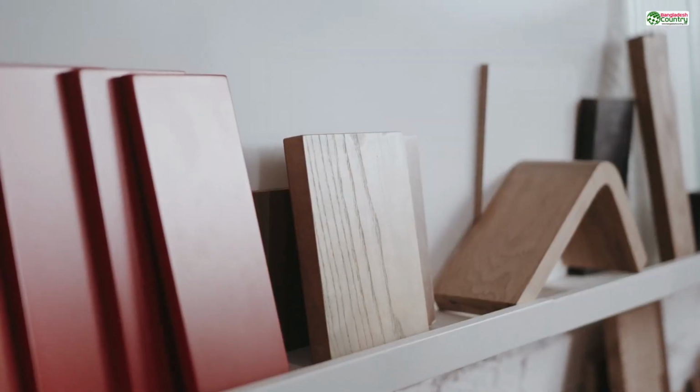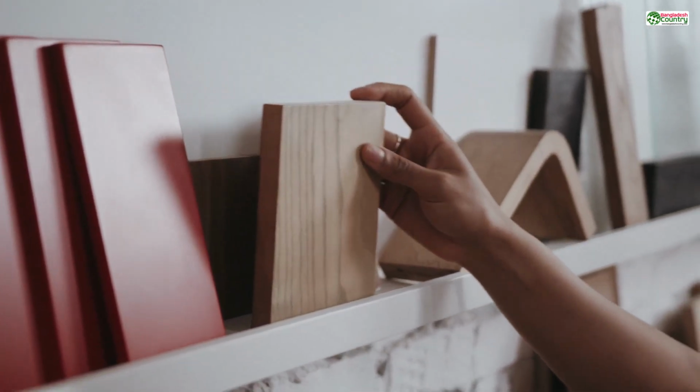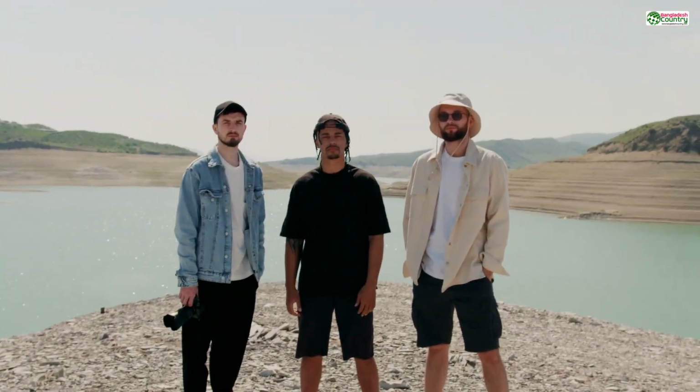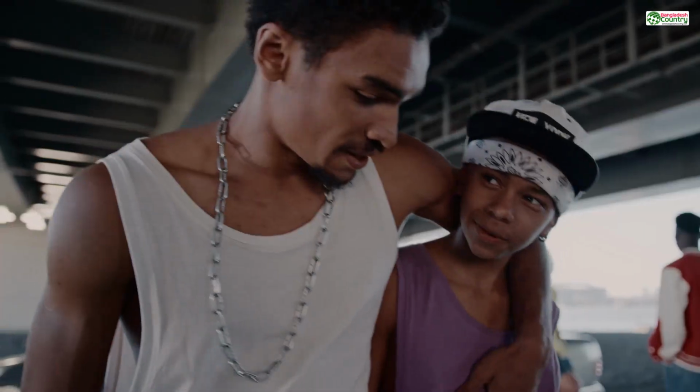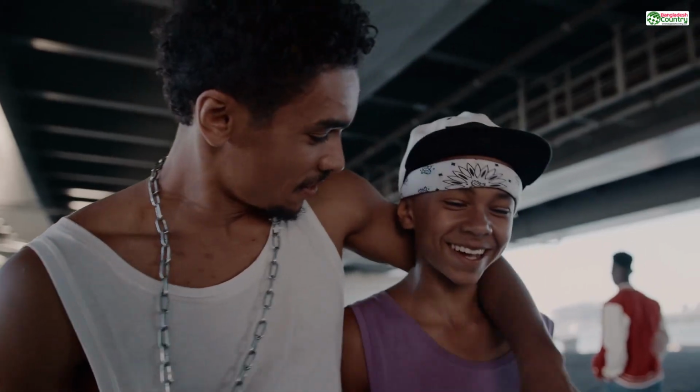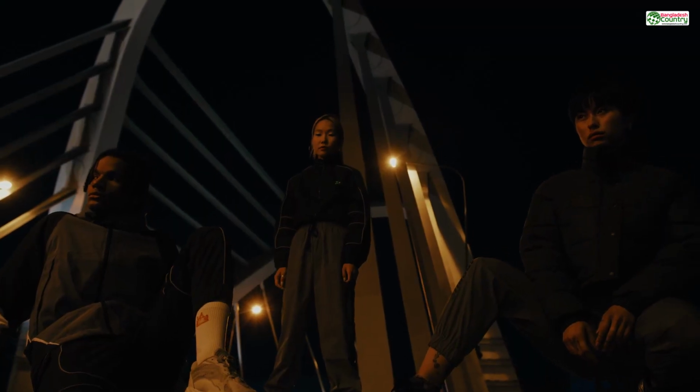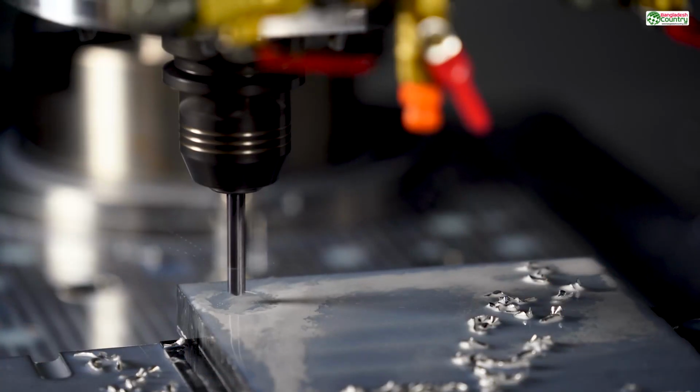They will tell you their recommended minimum diameter for drain holes for each material. Don't guess. They know their machines and materials better than anyone. They might say you need two 5mm holes for this resin, or two 10mm holes for that material. Follow their guidance. It will save you from failure.